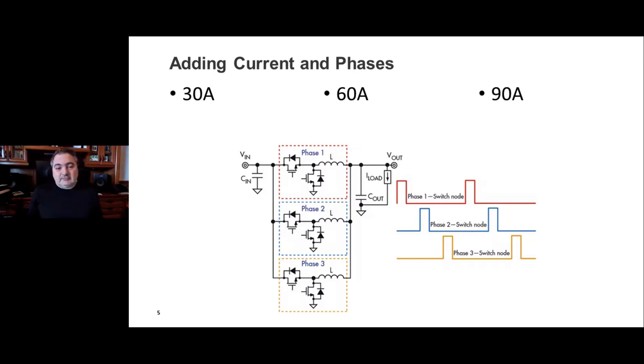Remember, the power management solution is running in a completely different clock domain than the chip. They're not synchronized to each other. So if you ever tested a power management solution, you can hit it with a pulse, and once in every few hundred or 50 pulses, you'll get a big old glitch.